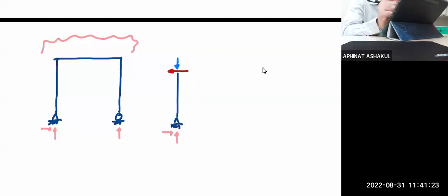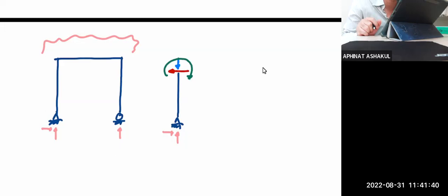This couple gives you the counterclockwise rotation, right? Can you feel that this couple gives you the counterclockwise rotation? So without any calculation, you know right away that you will probably need clockwise moment to balance this free-body diagram. Simple as that.